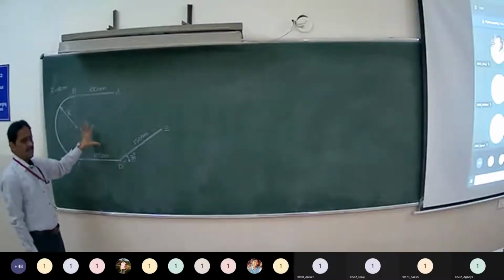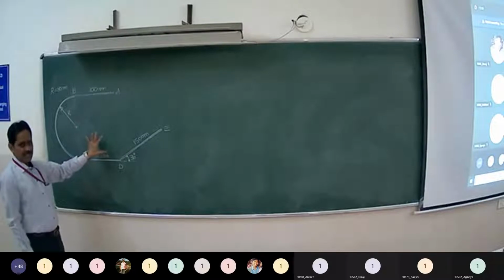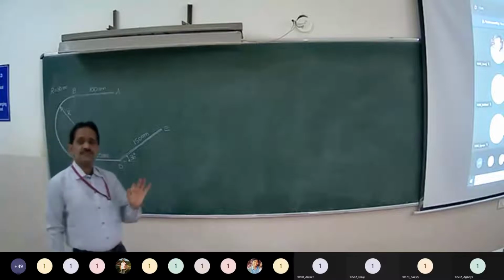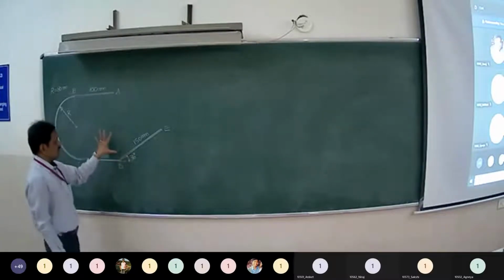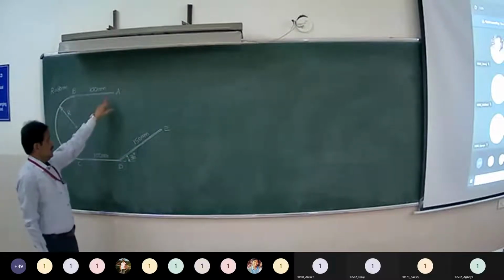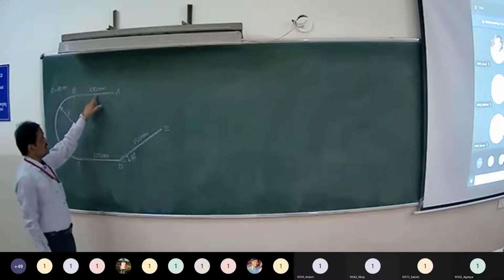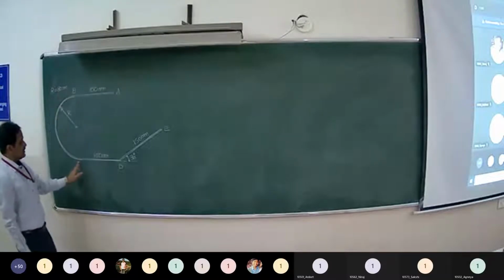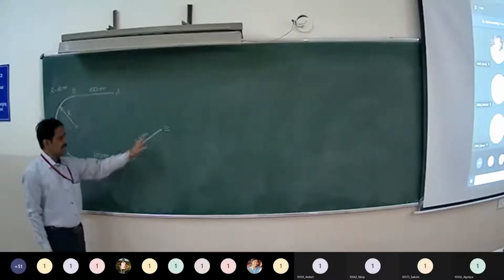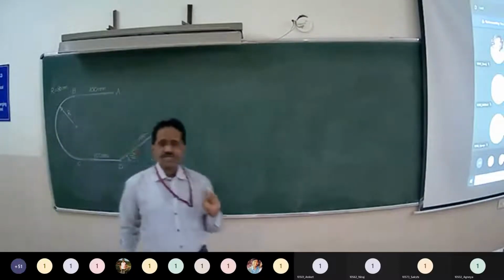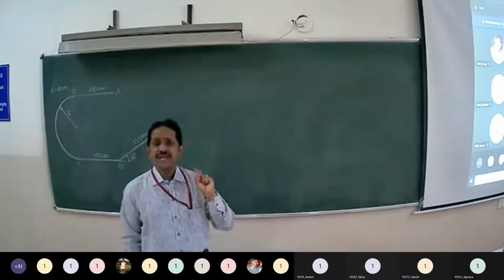So it is a one-dimensional body. For a one-dimensional body which is made up of homogeneous material, the center of gravity of the body coincides with the centroid of the line. So simply you have to find out the centroid of the given line. Length of this AB is 100 millimeters, and there is a semicircular arc of radius 80 millimeters, CD 100 millimeters and DE 150 millimeters.